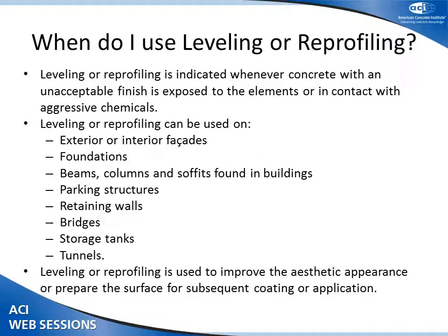First, when do I use the leveling materials? Leveling materials are going to be used whenever I have an unacceptable finish, either exposed to the elements or to a chemical, aggressive environment. Leveling materials will be used on exterior or interior facades, foundations, beams, columns, soffits, parking structures, retaining walls, jersey barriers, bridges, storage tanks, tunnels. Once we have the surface either leveled or reprofiled, it allows us to properly install, or gives a sound foundation for, an aesthetic or protective coating.